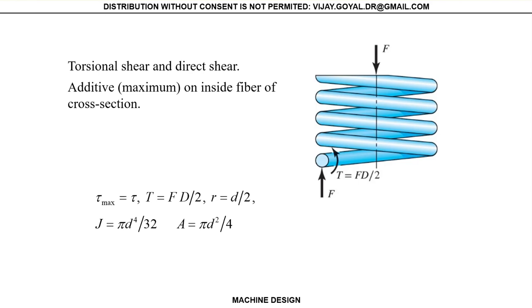Okay, so we want to find what tau we will use in your problem, and I took a small torsional value there, right? And now in the problem, again, just looking at the critical point, it can be here at the corners, right? Because I have shear. It's not the top and the bottom because I don't have a moment. I have a torsion. These are the two points I'm using. This is going like this. This is going up. My torsion is going this direction.